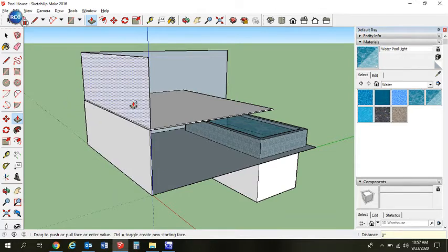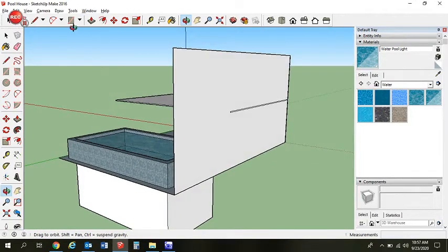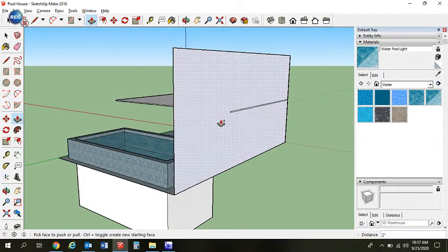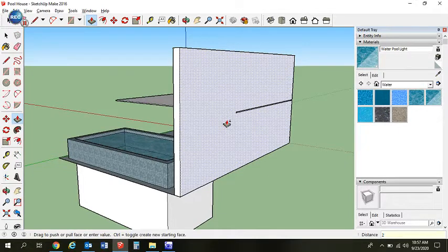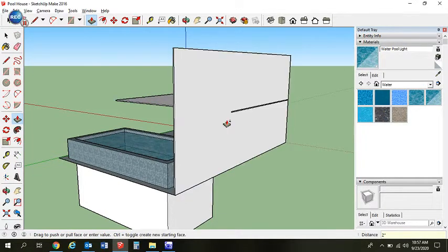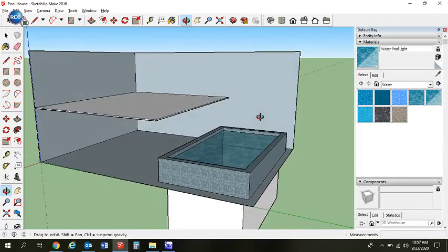And actually, if you just double click now, you can redo that same push-pull. Normally, it didn't work for me. So I'm going to go again. I'm going to line it up with this face. Perfect. Okay. Same on this side. So push, pull, 2 inches, enter, and done.